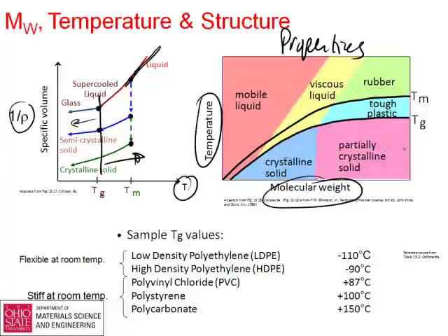As temperature goes up, if you get above the glass transition temperature, certainly above the melting temperature, you do not see crystalline materials as much anymore. Basically, by definition, when you get above the melting temperature, crystals won't persist anymore. But you can get these tough plastics here that are somewhat pliable through here, like Tygon tubes you've played with, which are above the glass transition temperature but well below the melting temperature.